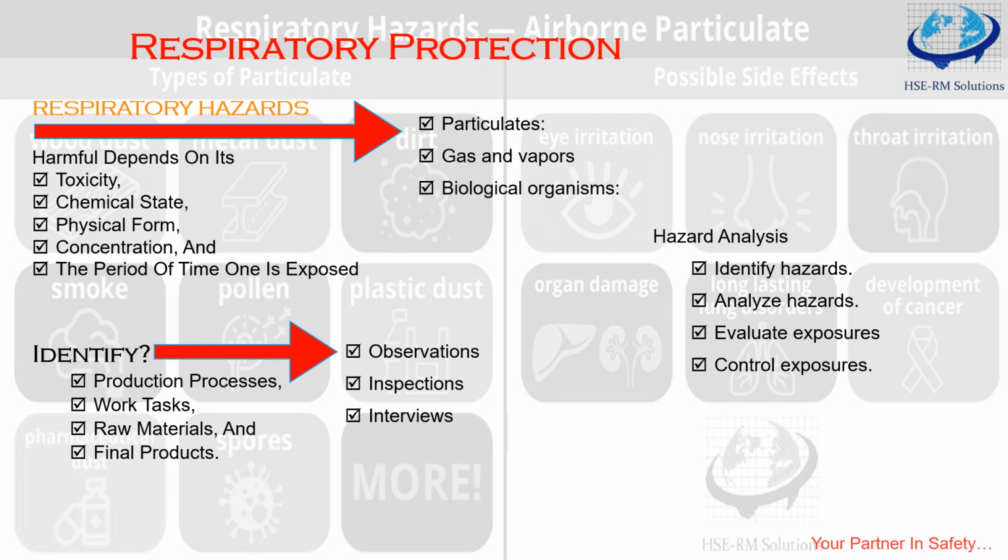After you have gained a good understanding through identification and analysis of the air contaminants in your workplace, it's important to evaluate each air contaminant to see if respiratory protection is required. To evaluate the impact of employee exposure, trained specialists such as industrial hygienists gather data about the actual exposure and compare those measurements against OSHA's established permissible exposure limits, PELs.